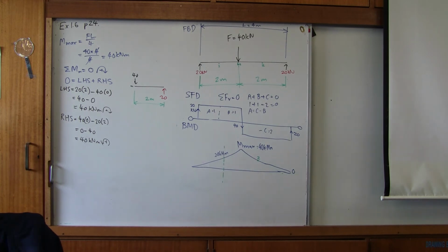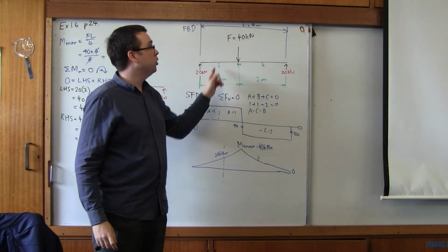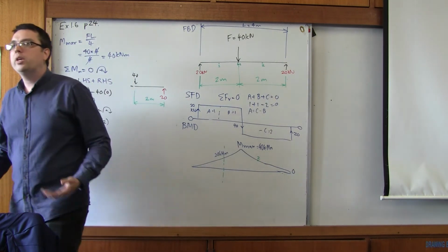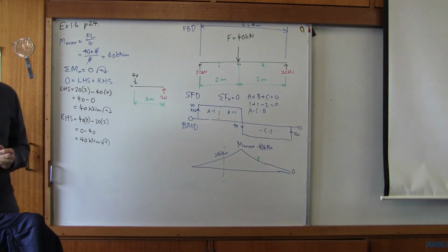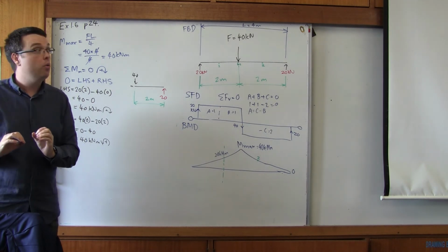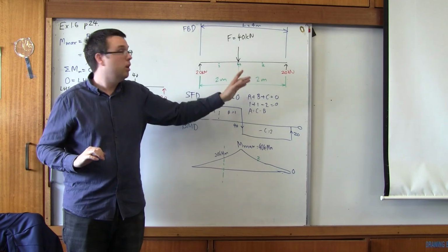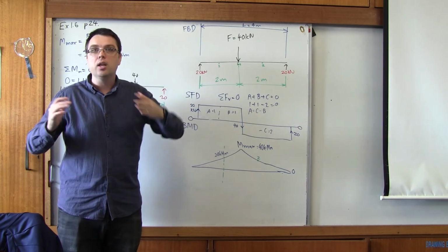So, we can use this formula, FL on 4, right? Occasionally people make silly mistakes, like using 2 instead of 4. But we can use that formula, though it only works in a very, very specific circumstance, where we have a symmetrical loading with the force in the middle.